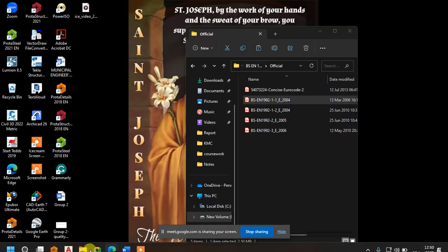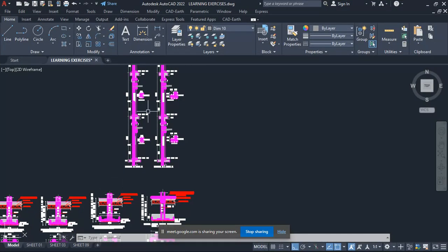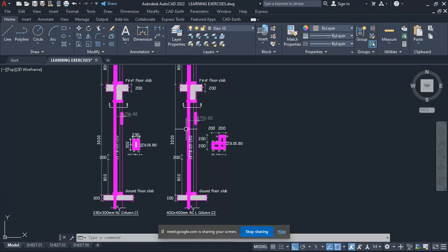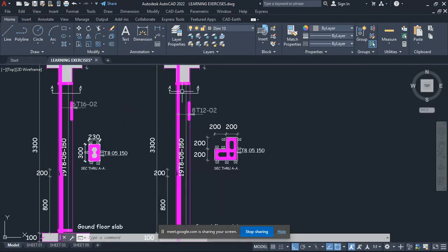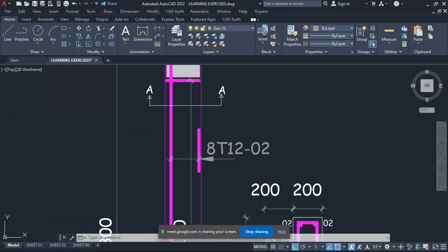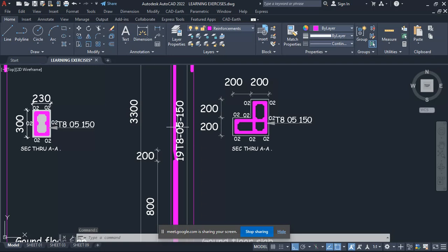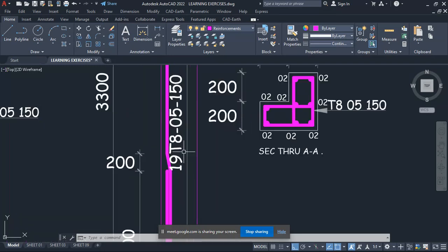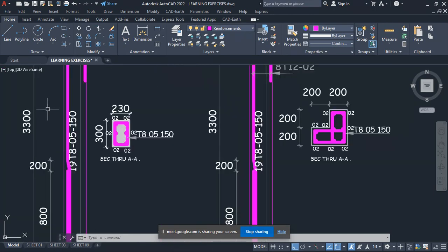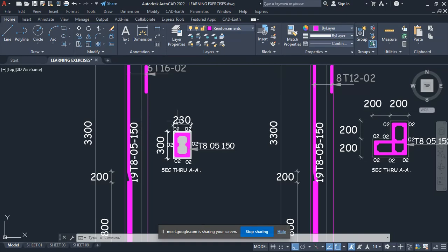So as I was still showing you, I had them at 150. You can estimate the distance between the beam and the ground, then you divide by 150 and you get the number of them. So this is 19 T10 bar Mark 5 spacing 150. Okay. We are here.